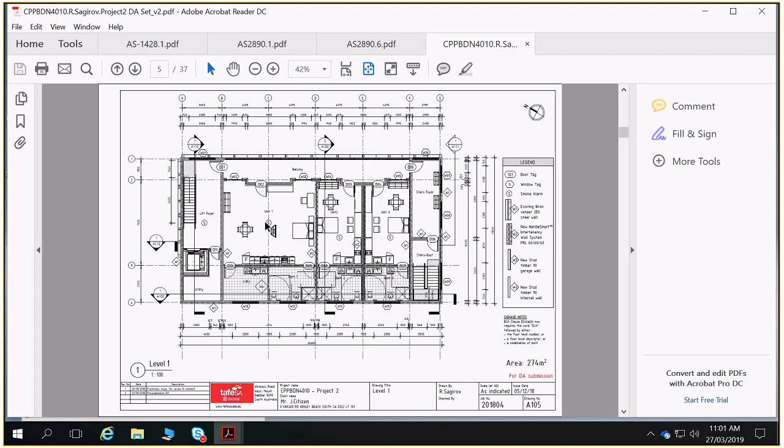But what our client wants us to do, or what the brief stipulates, is that you produce 1 apartment which is designed for disabled access. What the National Construction Code then ends up telling us, and I'm not quoting the NCC, I'm just trying to summarise it, is that if you have a building in which you have disabled access, then all the other parts of that building to which that disabled person may reasonably be expected to enter have to be made compliant to disabled access as well.